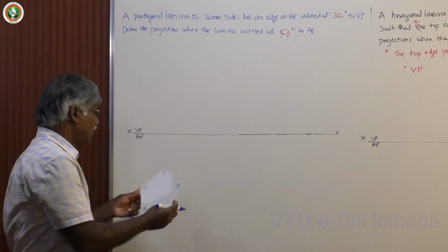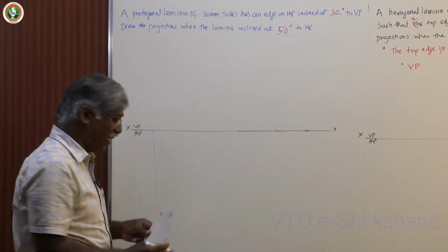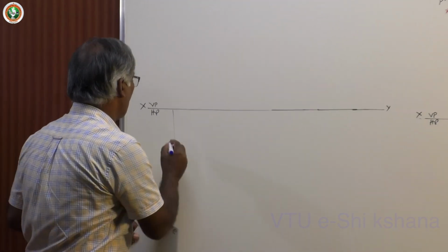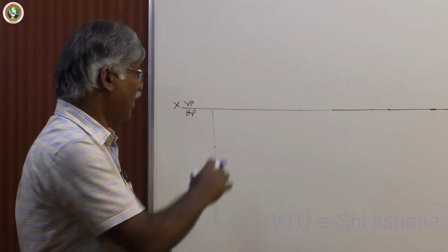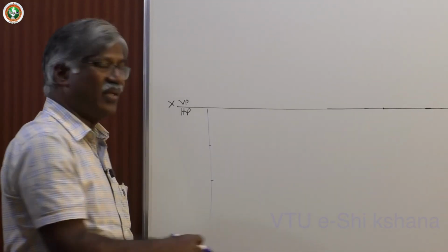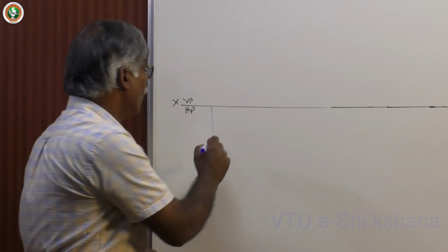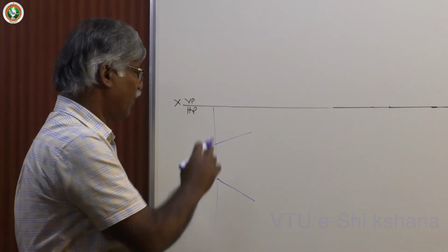So see, this is how you do it on a particular line, perpendicular line. You must have this AB, then do it. How to do manually? You have to mark 30 mm, a little away from it, so that you can accommodate the entire figure. Then 108 degrees, 108 degrees. Take carefully.